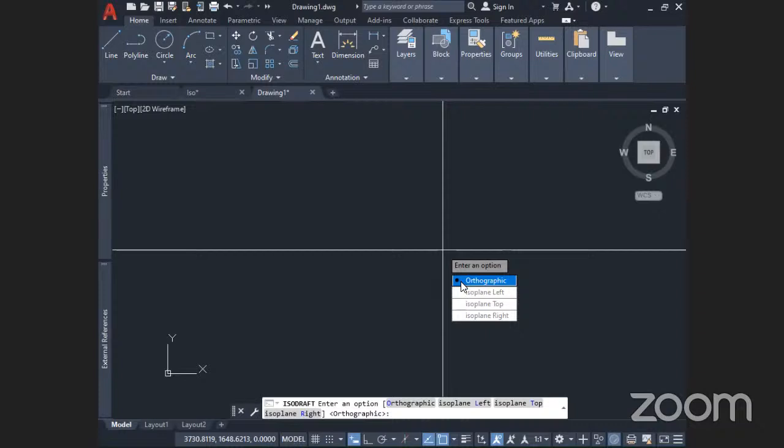What this means is that you can only use 2D projection here. If you're looking from the top, you only see the top view and you won't see other sides. If you're looking from the left, you only see the left view, and from the right, only the right view. That's what it means, it's using the orthographic projection. Now you want to make sure it is in any of these, so you want to turn any of these on. You have to remove it from the orthographic projection. Do you understand? If you understand this, please type understood as we move on.